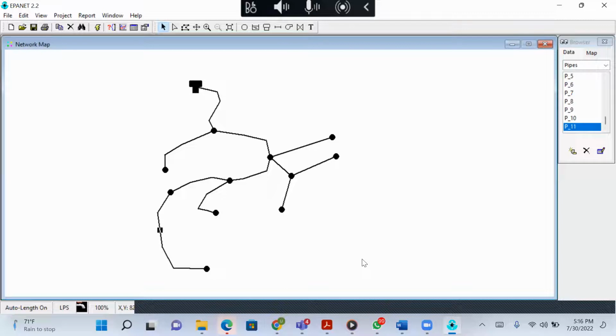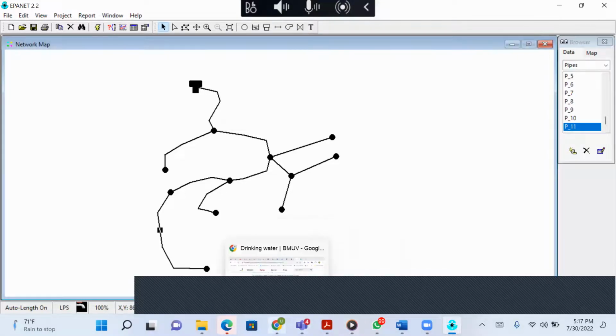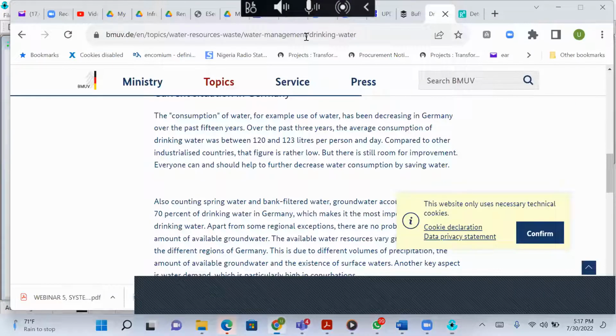Yes, you can use it, but the challenge you're going to have is that this is for subsurface pipes, right? So for your storm design, you can use trapezoidal, you can use open drains. This one does not accommodate that. But in the next 3 weeks, we're going to see the one for pipes. It's called SWMM, Stormwater Management Model. We download it from EPA.